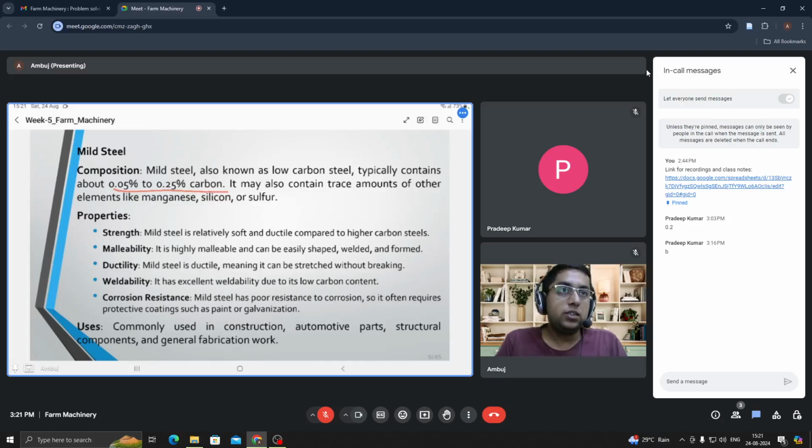Just a quick question. I have not told you every type of steel, but at this point I just wanted to ask one particular question. In mild steel, the ductility is high. And in other high carbon steels, the carbon percentage would be larger, so ductility would be somewhat less and hardness would increase.